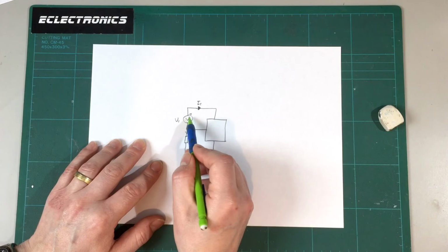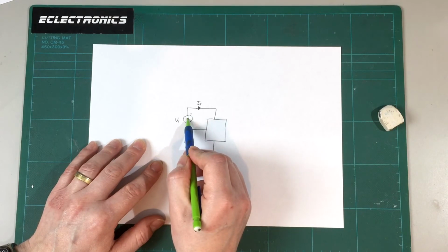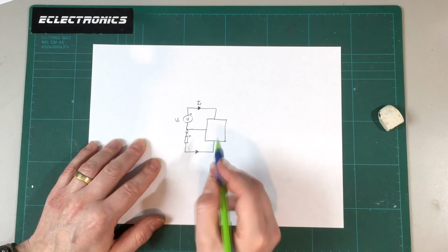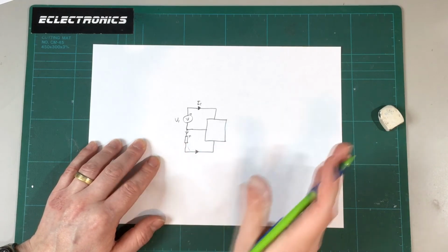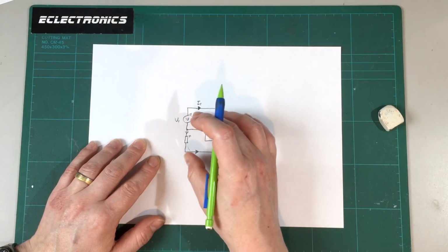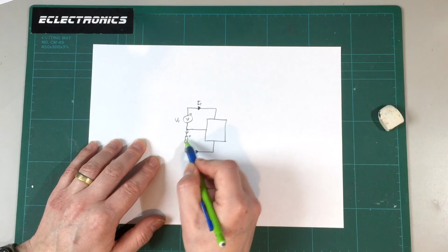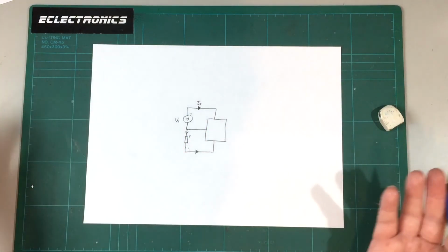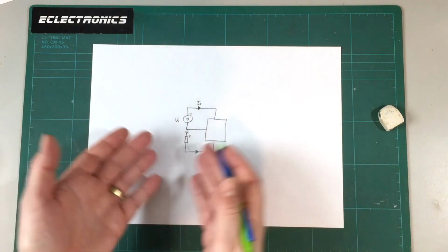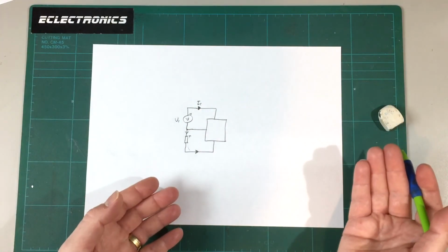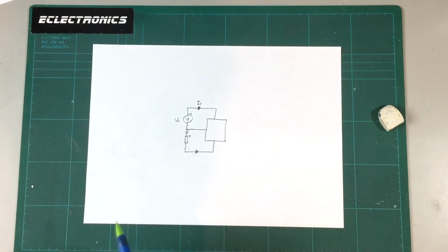So we'd be transferring energy from a power supply up here in this position to a resistive load down in this position. So this may work, but it may be a little bit difficult to control because the current through here is going to be dependent on the voltage difference, but we're not really controlling the voltage down here. It's just a resistor, so the voltage is directly proportional to the current. So depending on what current ends up flowing, gives us our voltage, which then gives us our voltage differential, which may determine our current. So this may not be a stable way of measuring the characteristic.